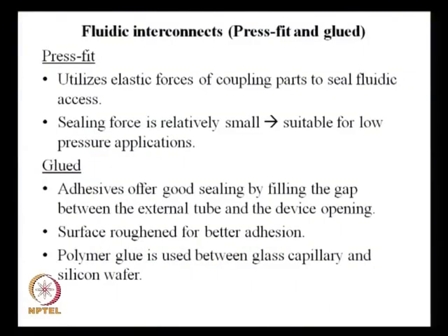At the very outset I said these epoxies and these UV curable glues, these are very effective. If somebody is using it for a small scale, I mean if it is a moderate pressure and if he is not fussy about keeping things very pure, these polymer glues are perfect for these applications. So, press fit and glued, these are the two types of interconnects that you understand.